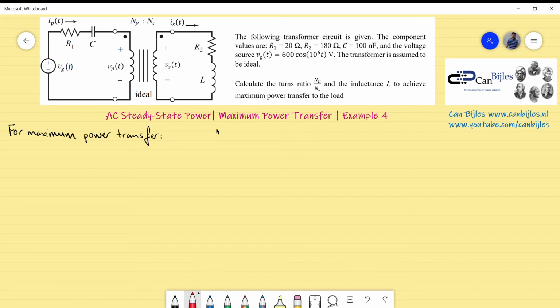Now what you should do in this circuit is look at the reflected impedance. That's actually also an important topic. So this impedance, looking into the primary side of your transformer, is a reflected impedance. I will define it as Z of L prime, the impedance reflected from the secondary side to the primary side. I will first determine the expression for that, and its complex conjugate must equal the expression of the source impedance. So I will write it down in more detail here.